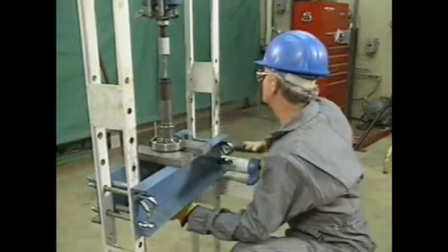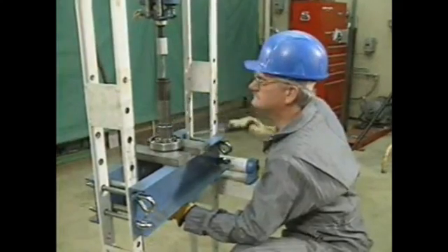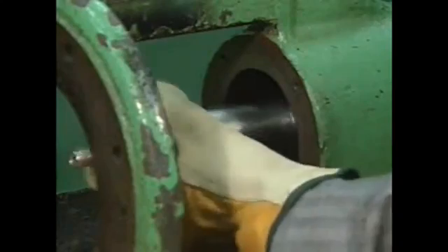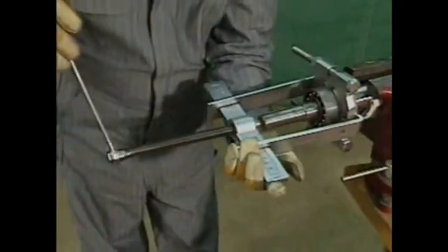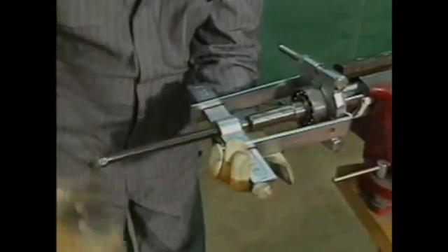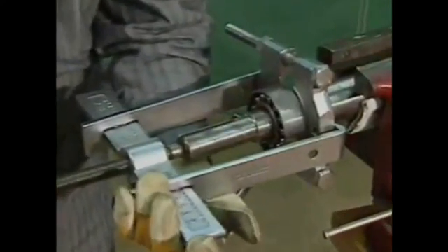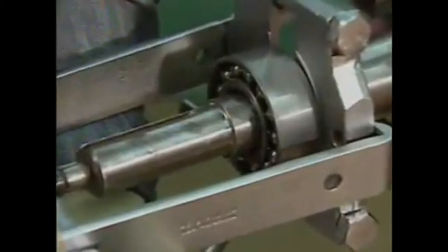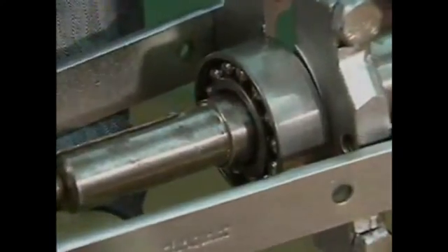Rolling contact bearings are usually installed with a press fit on one ring and a push fit on the other. Removing a bearing that has been installed with a push fit is relatively simple because it is a loose fit. Removing a bearing that has been installed on a shaft with a press fit is more difficult because it is a tight fit. The principles involved in removing a bearing that was installed with a press fit are the same, whether it is the outer ring or the inner ring that has the press fit.